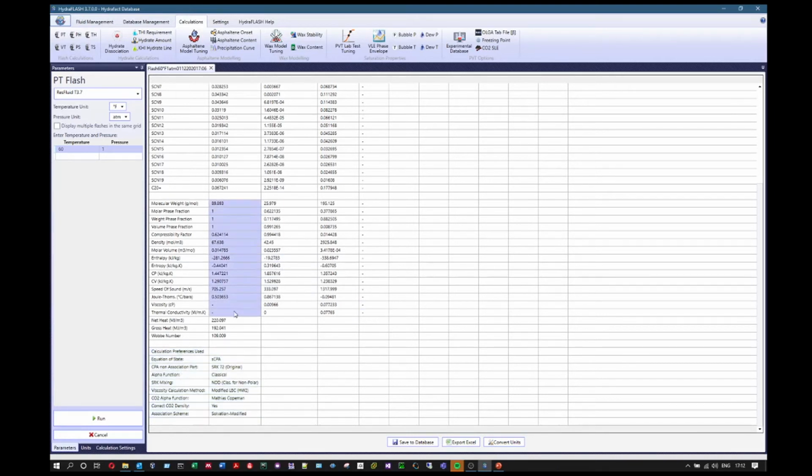In this column, you will see the properties of the feed of the total system. So if you want to know what is the enthalpy of a multi-phase system, you need to perform a flash calculation and read this part.